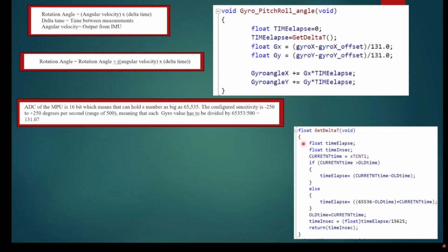So now let's look at the delta time. What I'm doing here is something that I've showed you in the timer presentation. So I read the time. One of the things is that as I read, the timer is going to get to a point where it's going to roll over, and that's 65,536 because I'm using the 16-bit timer, so I have to account for that.